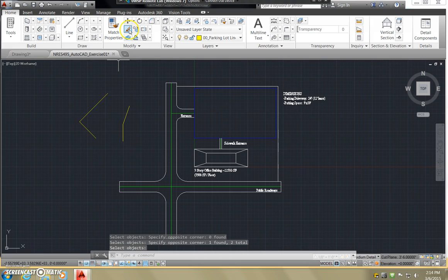One of the things that I suggest is that you can certainly also find the erase tool up here at the top. It says erase up here, and I can do the same thing where I click on this. But if I look at the command line down here at the bottom, I can see that for erase, it says select objects. When I'm done with that, I hit the space bar, and it goes through with the command. There are a number of different AutoCAD commands that are going to require you to look at the instructions on that command line. So this space down here becomes really important. First off, I'm going to do an erase and erase that line I just drew.